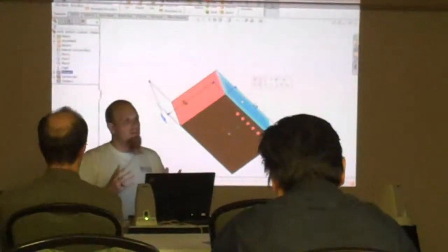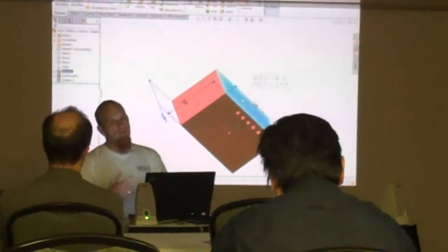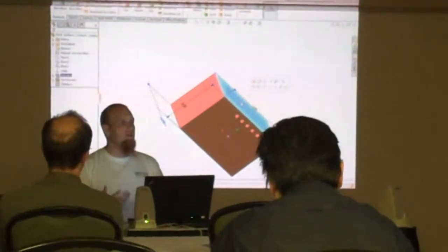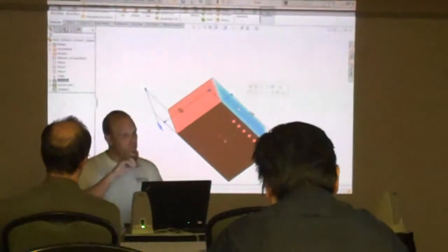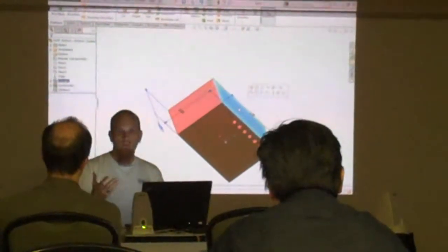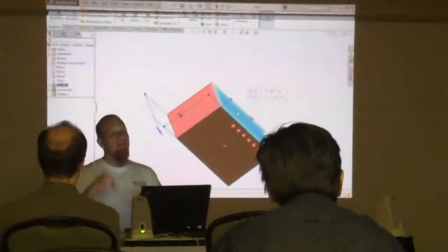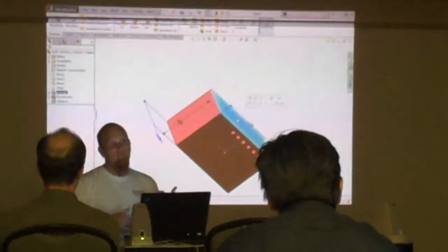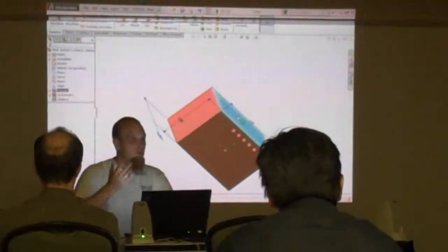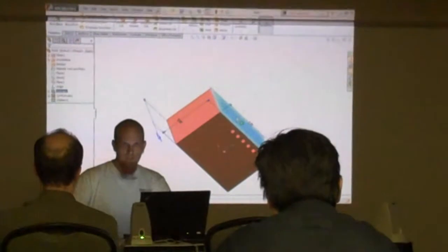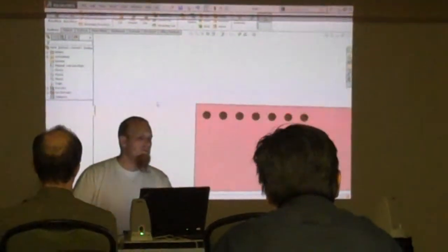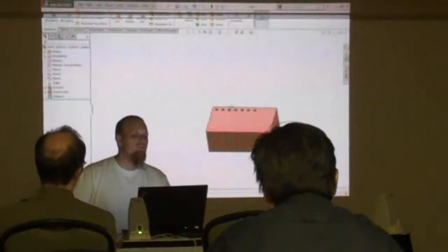When the design changes and say, oh wait, the 1/4-inch isn't available, we need to change them all to 3/8-inch holes now. Now you got to make sure you go to all the different faces and hit all of the 1/4 inches, because there is no, like I showed with the fillet expert, for that. You could do an equation, but then you got to wait for that to rebuild every single time. So what we can do here is use what's called a derived sketch.